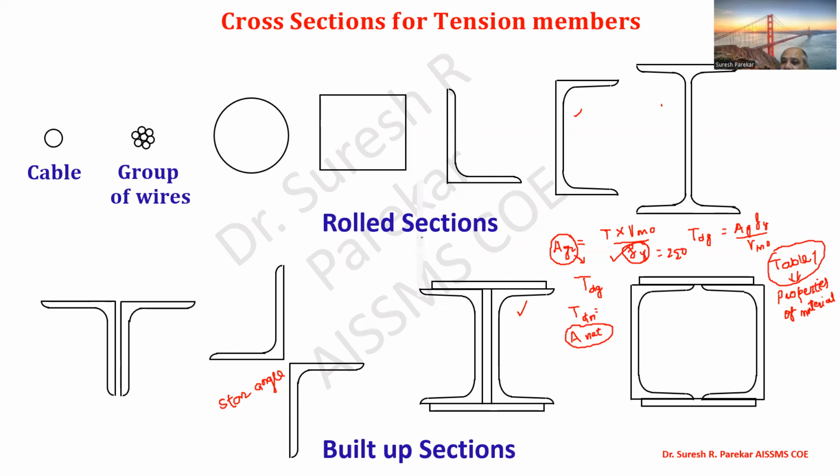That is table 1 we have for properties, table 2 for classification of section, and then table 3 slenderness ratio. Table 4 and table 5 we have partial safety factors for materials and for loads. Then table 6 is the deflection limit. Likewise we have these different tables, and we should know table 7 imperfection factor, then 8 ABCD we have reduction factor, 9 ABCD we have FCD. Likewise we have table 10 buckling class, 11 slenderness ratio.